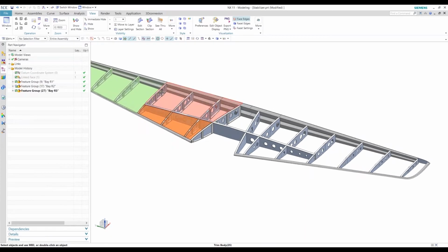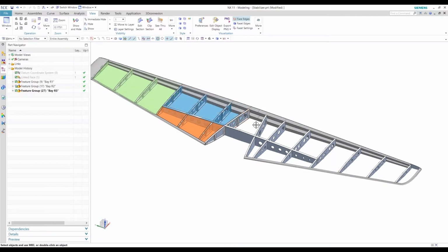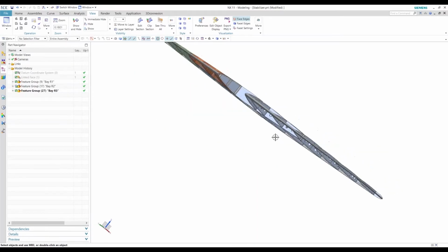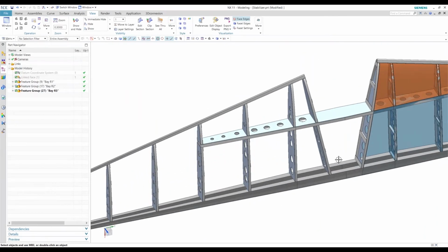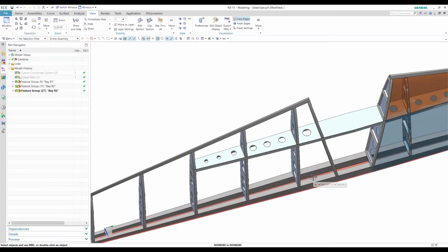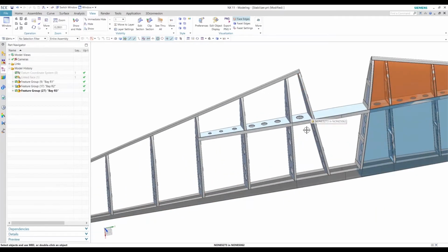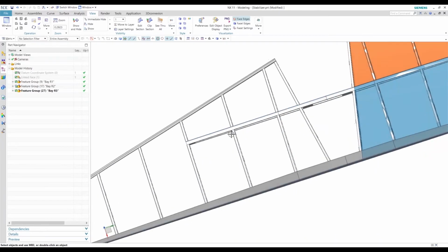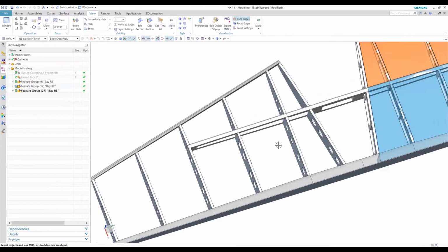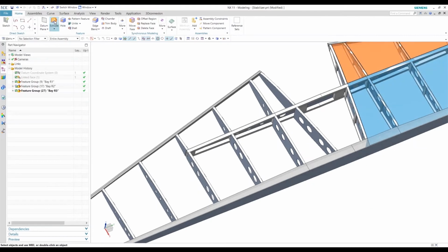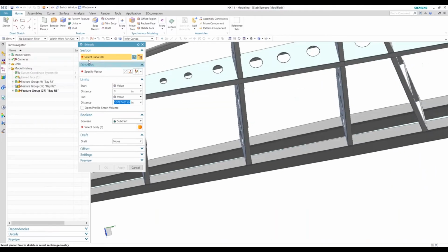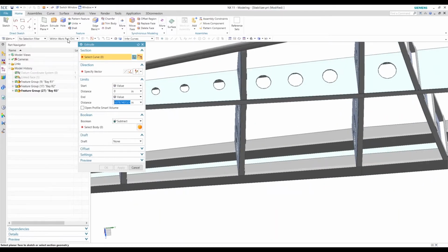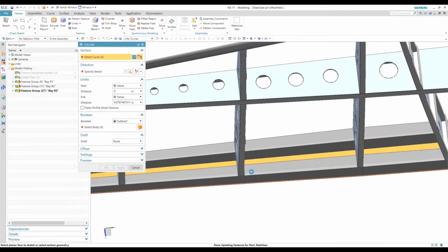So that covers the first 3 inner bays here. So I know I want to capture these 3 bays here. So I'll start with an extruded body on this surface, work my way up, and then start trimming so I get an accurate representation of the inside of that volume. So I can use the extrude feature, click on my surface. If nothing shows up, you'll want to change your selection filter here to entire assembly.